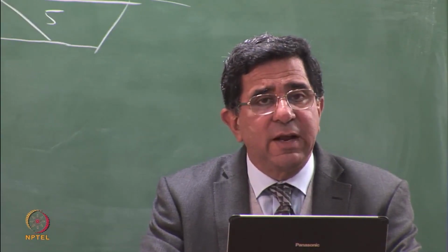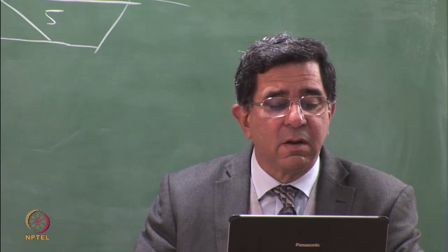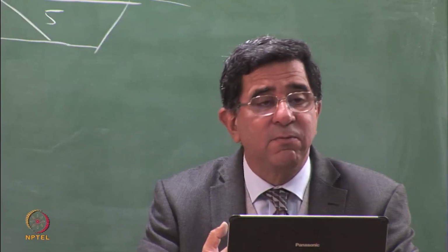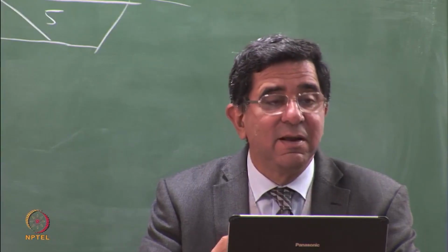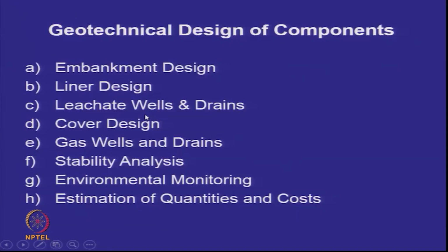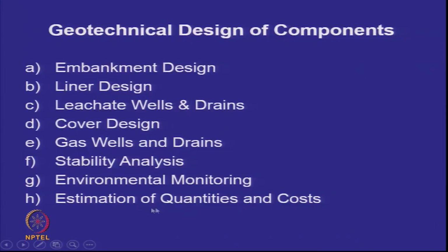We have to do the geotechnical design of many components, and this is what we will cover in this course: embankment design, liner design, leachate wells and drains. We will not be doing the hydraulic design, so we are not going to do open channel design, pipe flow design, pump design, or estimation of floods. What we'll do is the geotechnical design: the wells, the cover design, the gas wells, stability analysis, and environmental monitoring. The bulk of the cost of a landfill is in operations like waste placement, embankments and liners, so we look at how to estimate the quantities and costs of landfills.